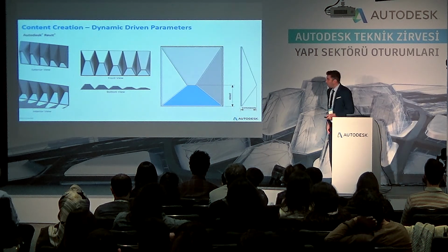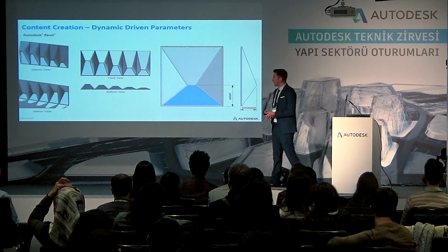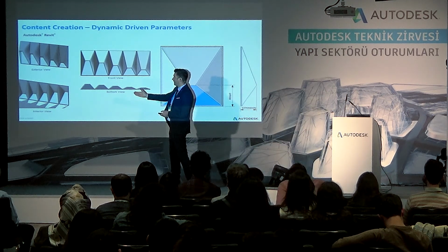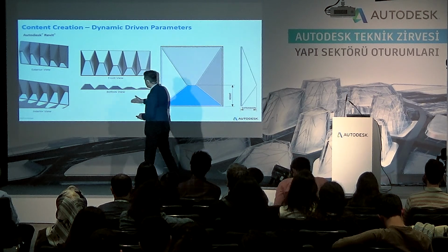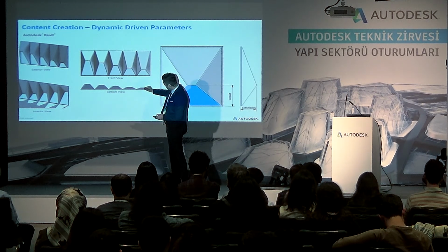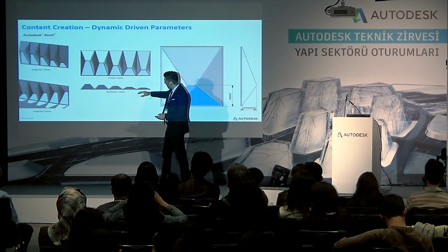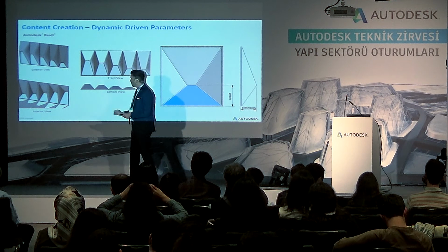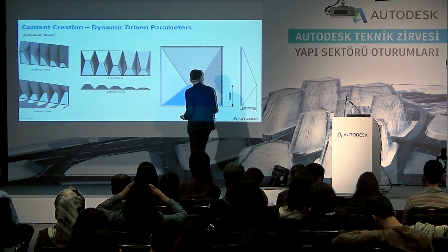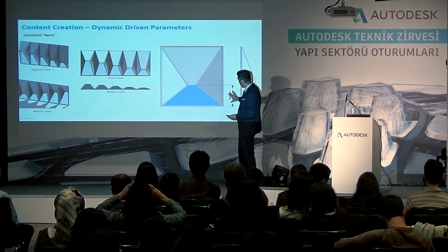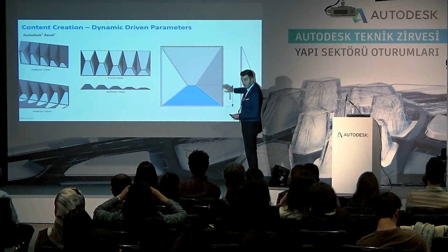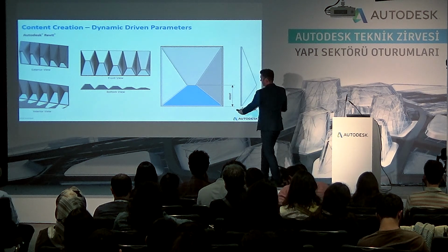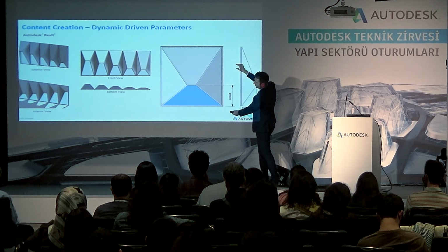Okay, so in Revit, we need to create some custom families. What we want to achieve is this kind of effect. These panels, seen from the top, can have different heights and also different elevations of the opening. So we need to create this family that has this parameter flexible and also this parameter flexible. So we can stretch this one, and we can stretch this one, okay?